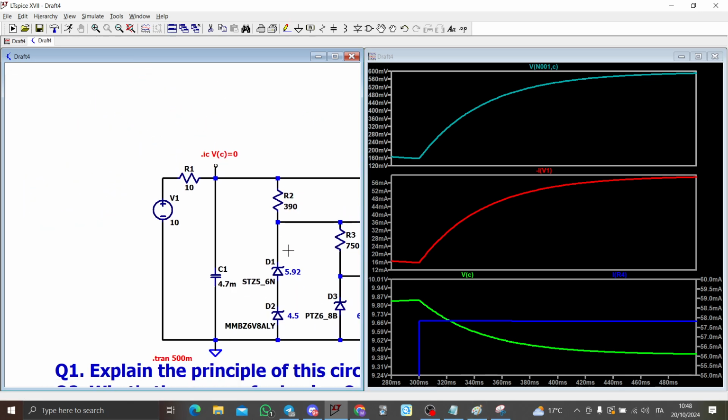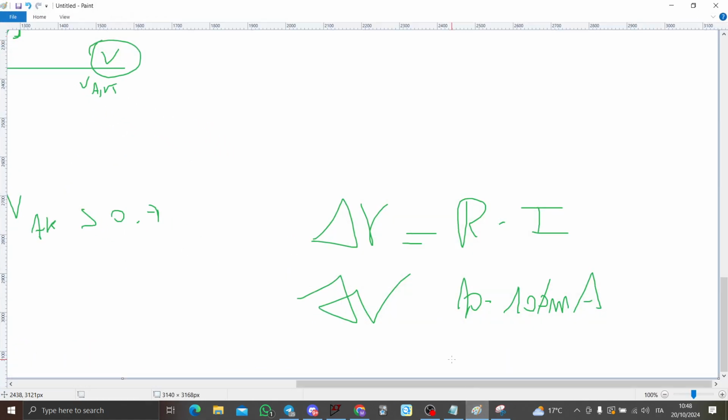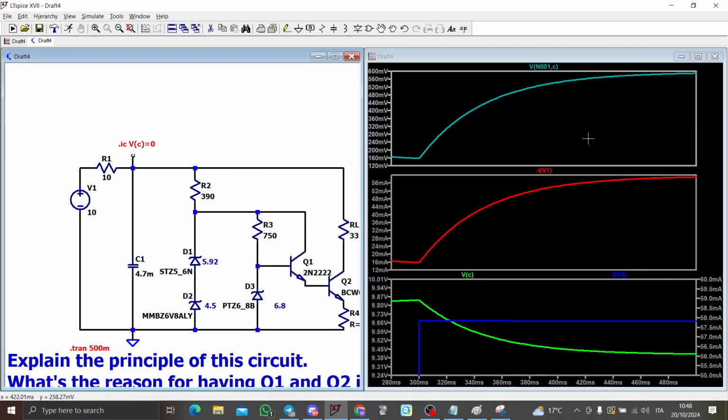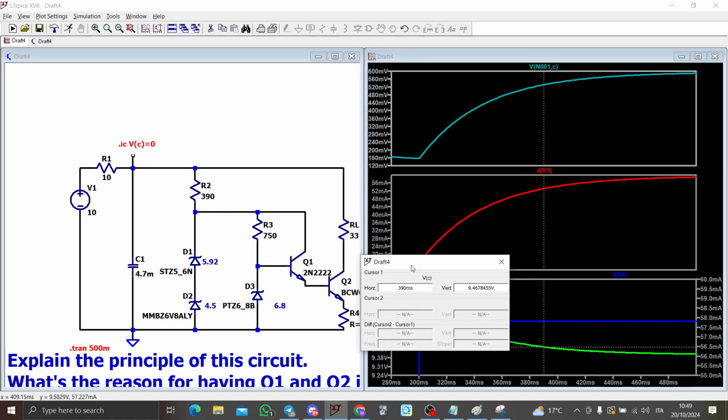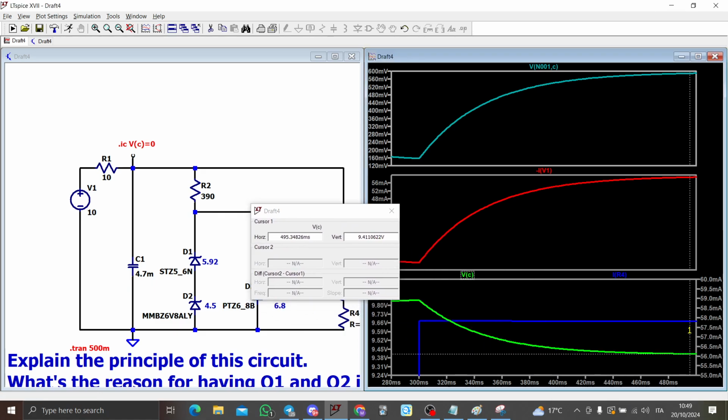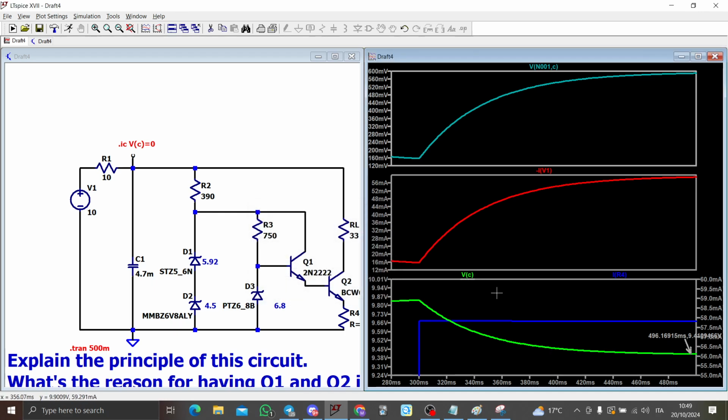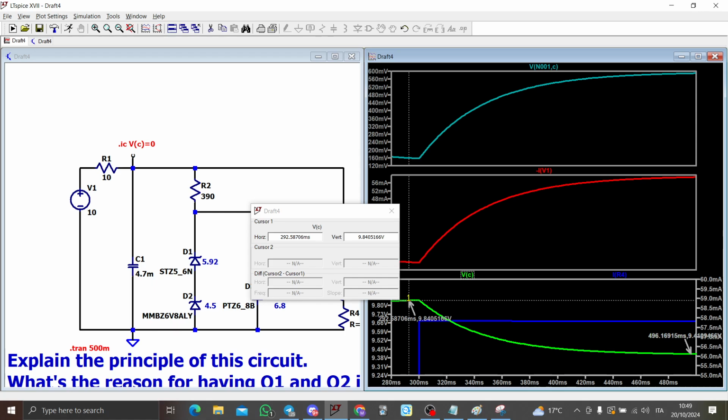Remember, it is nothing difficult. It's just using the principle that the capacitor is giving you current I, because it has to give you charge, and then this current flowing into here will create a permanent drop voltage on this node VC here. So it is also important to use the basic equation to understand what to expect at the end of the transient. After the end of the transient, we have a voltage of 90.41 in a very, very calm situation. So from 90.4 to 90.41.